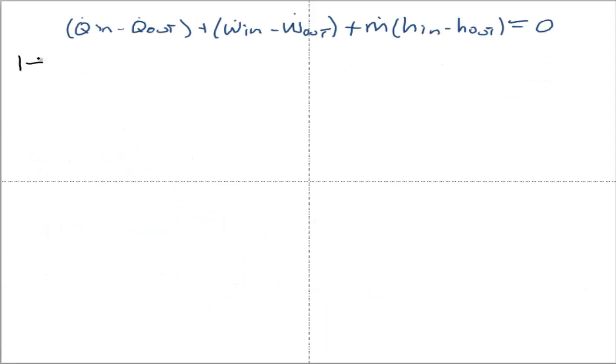Our first component to analyze will be process 1 to 2, which is an isentropic pump. Recall the TS diagram that we defined. For this pump we don't have any Q interaction, no heat going in or out of the pump, so we cancel this term.